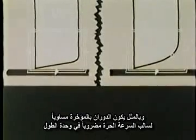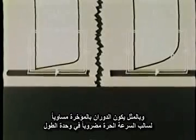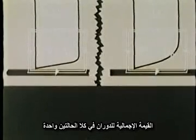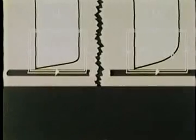Downstream, the circulation is also equal to minus u naught times a unit length. The total amount of vorticity within each contour is the same. Because there is no vorticity upstream of the plate, and because the circulation per unit length along it is constant, we conclude that all of the vorticity is generated along its length.